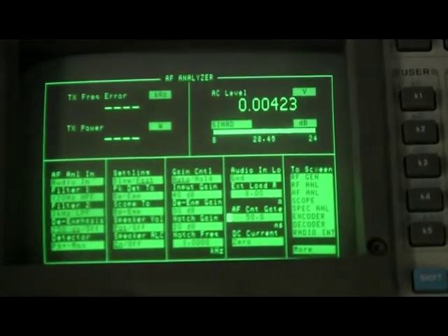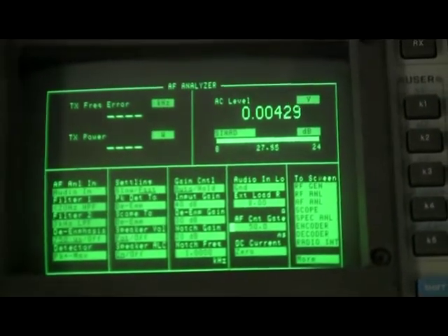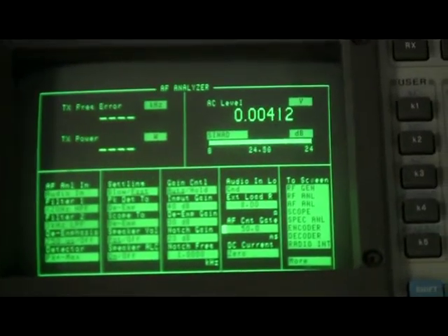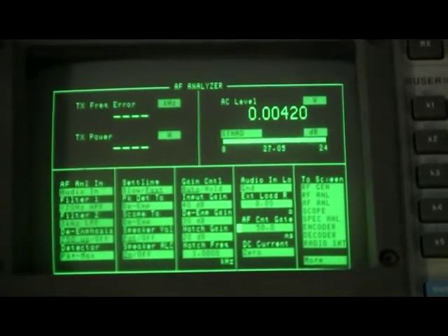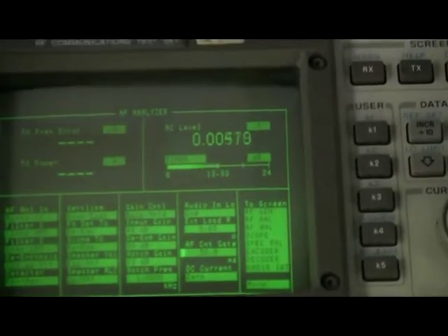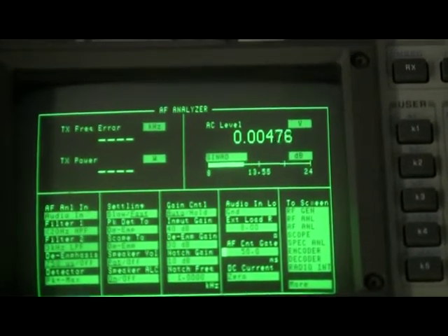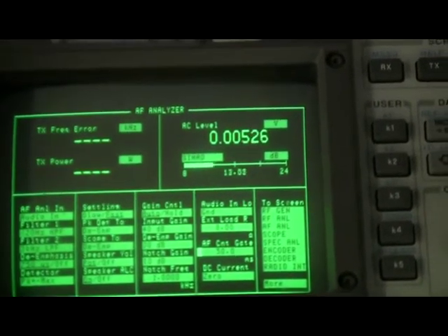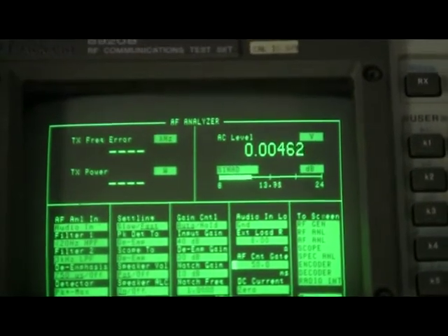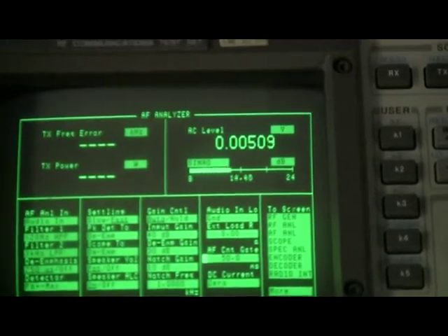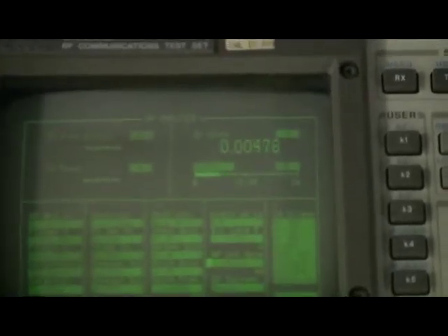But to quantify how much we've mitigated, let's add some additional attenuation. I'll add 10 dB more, and we see we're still in the 20s, and I'll add 5 dB more. We're in the 18, so we've added a total of 15. Let's add 3 more, which would be a total of 18. So that's 18 dB we've added beyond the 20 we had previously. It's still a little high. Let's add 1 dB, which would be a total of 19. And I'm going to call that 12 dB. So we've added an additional 19 dB of attenuation on the uplink transmitter and still achieve our 12 dB of output SINAD.